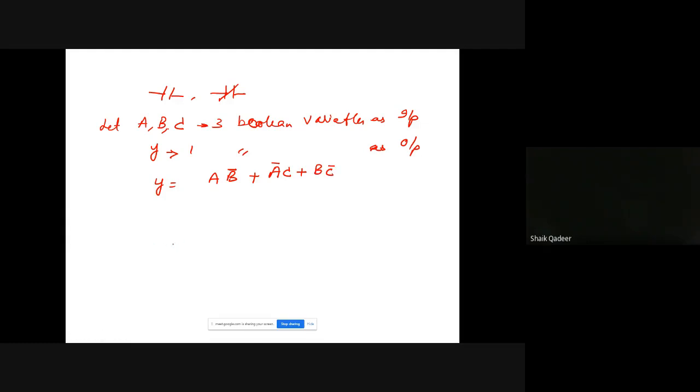Okay. So in order to realize this type of logic in our ladder diagram using these two basic functions, this is called normally open, this is called normally close. We will write the logic like this, a rung like this. For A, I will use a rung like this. For OR logic, I will write the connection in parallel.